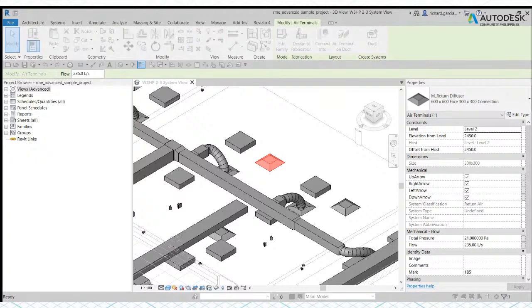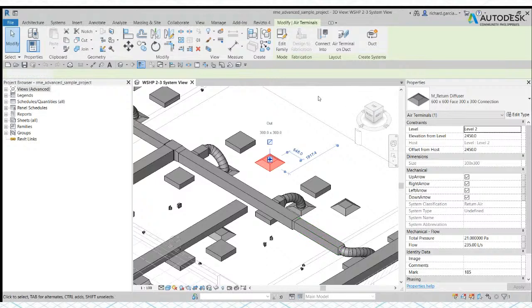So let's say, oh, I want to have a 900 one. Don't change that to 900 straight away. What you do is you duplicate it, and then put whatever name that you want, and then select OK. And then that's the time you can now change that to 900. By doing that, you will only be modifying this particular family here, and you are creating another type of family. Okay? So I hope that one is clear. So let me just cancel this one. So that's our properties. What else?